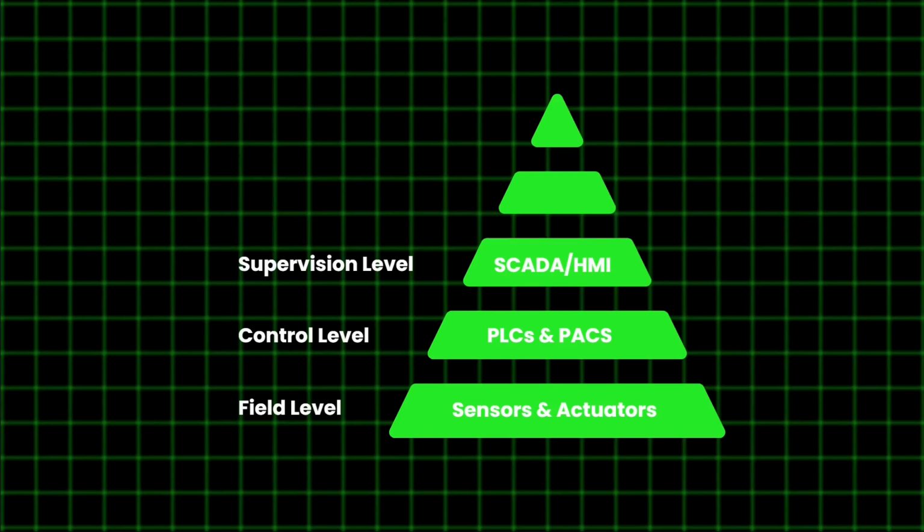This system is used to examine, collect, and process data in real time. Also within the SCADA software, there is the ability to log data for historical purposes. The data from the field devices are routed from the PLC or PAC to the SCADA computers, where the software interprets and displays the data to the HMI screens. The HMI screens are where the operator analyzes and directs the system's events.